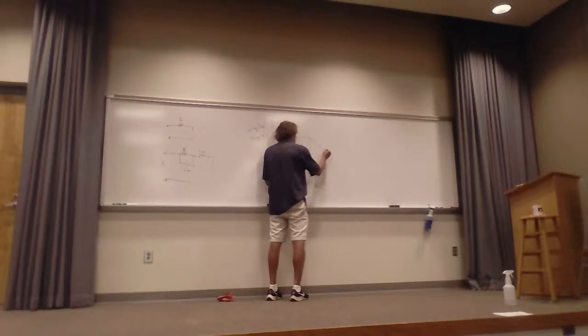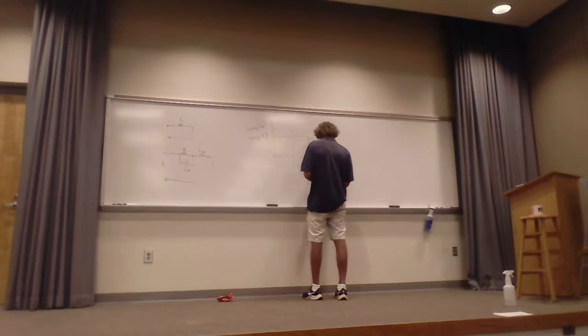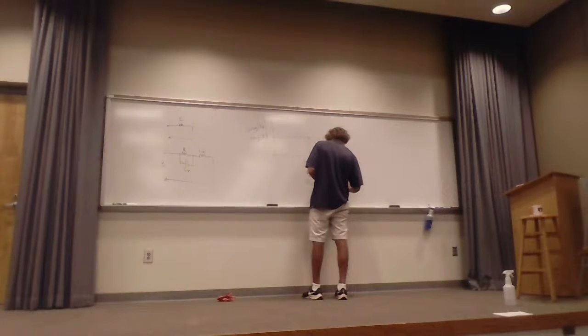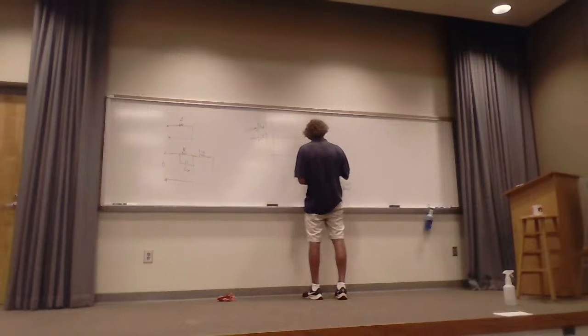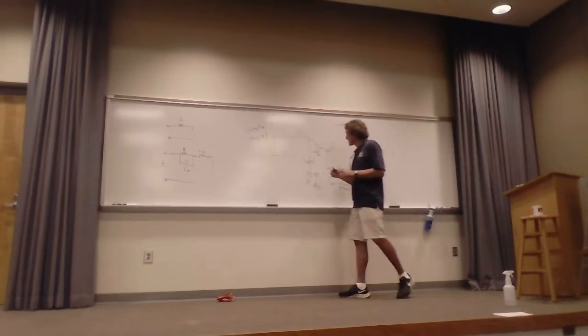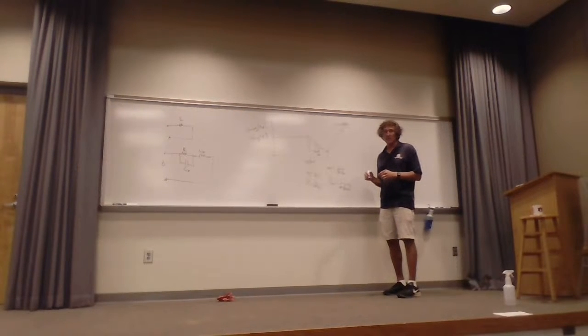And it'll start going down at a rate of minus 20 dB per decade here until it hits the self-resonance. And this will be just 1 over the square root of LC, or at F, self-resonance is equal to 1 over 2 pi square root of LXCX. And then after that point, it's going to start going up at plus 20 dB per decade. And that's what a resistor will look like all the time.